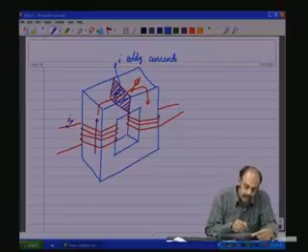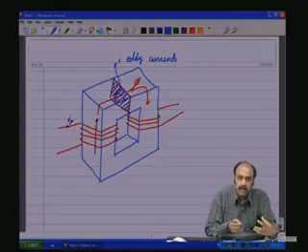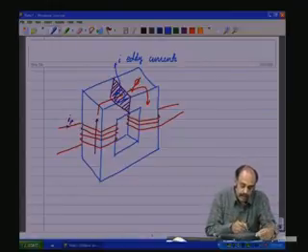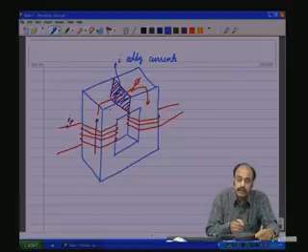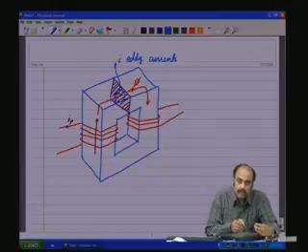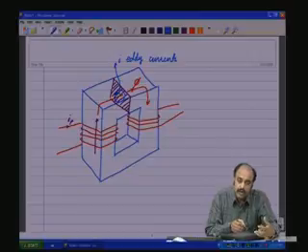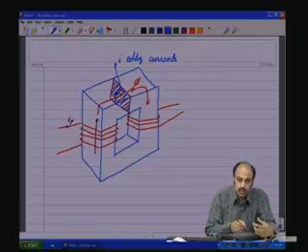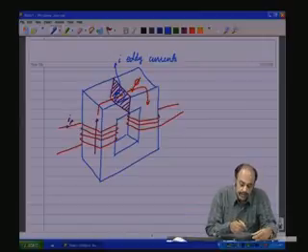These currents are flowing in the solid mass of the core, and if the mass of the core is highly conductive, then these currents could be quite high, because the resistance will be very low, and the I square loss, because it is dependent on the square of the I, will be very high, quite considerable.